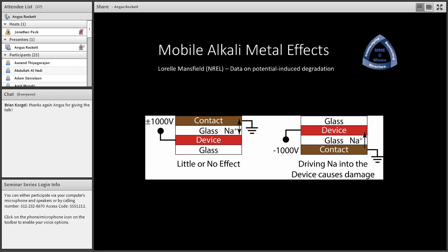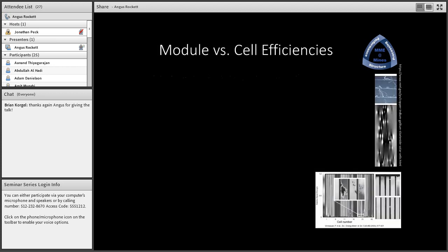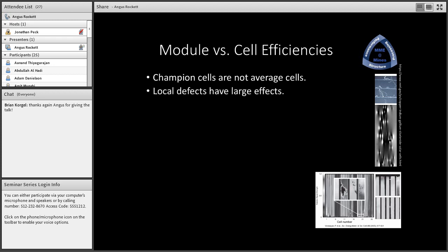And my CIGS array came with very specific instructions as to which side of the device to ground so that the exterior surface of the package would be negative relative to the device as much as possible. So this is quite important in maintaining operation of the device.